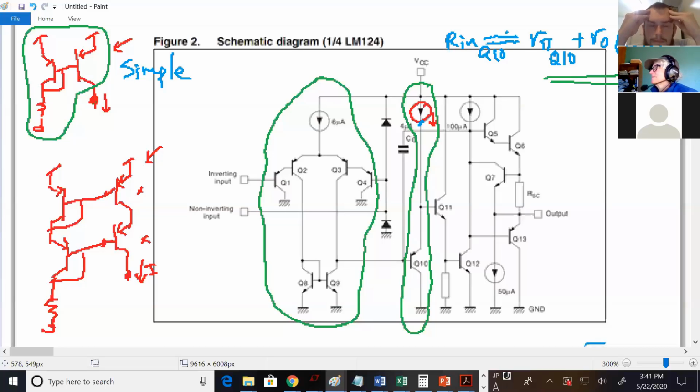So with really high current, you have really high Rn because of that 1 plus beta. Well, beta won't change. If In changes, I out will change. So beta doesn't change. So since R pi is beta VT over IC, a smaller IC will give you a bigger R pi. Yes, exactly.